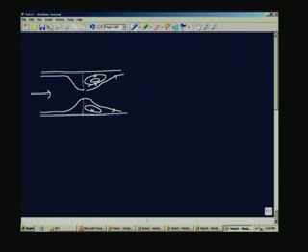And what happens in a circulation pattern? The kinetic energy is converted to internal energy, and therefore some amount of pressure head is swallowed up by this activity, and therefore the pressure recovery is not good, pressure recovery is poor.